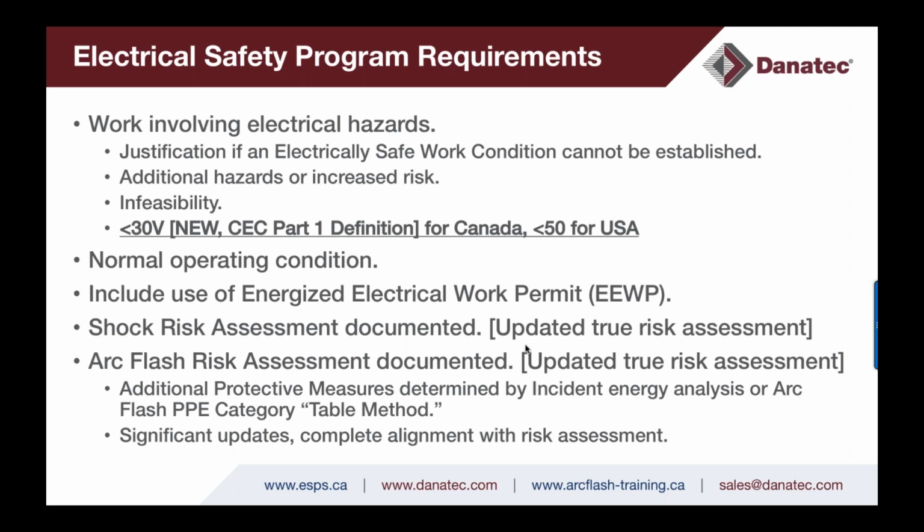Of course, your electrical safety program should identify the energized electrical work permit. I had that in the workflow process flowchart. Again, the requirements for it should be documented in your electrical safety program. When is the permit needed? When is it not needed?